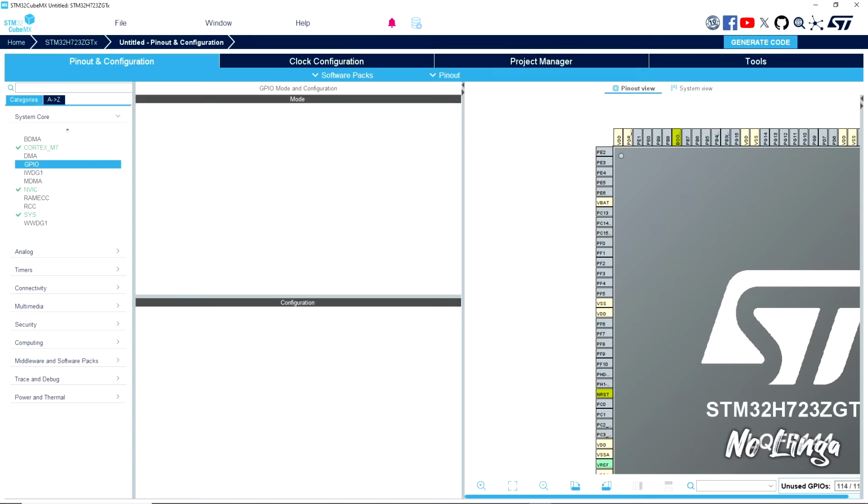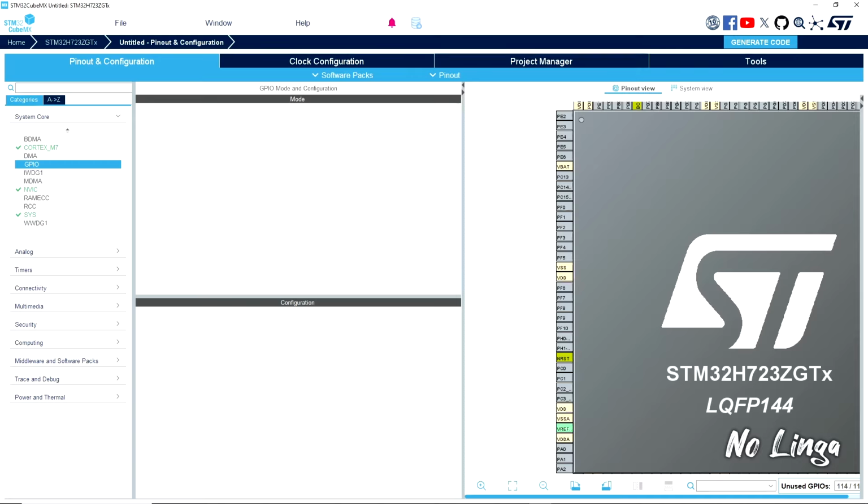I'm going to enable pins for the buttons that we already know, 4 buttons, including one of the encoder knobs, and the 2 encoder timers. And in addition to that, we'll go ahead and set up another timer. It will be an update timer, and we'll go over that some more. And so let's go ahead and get this going.